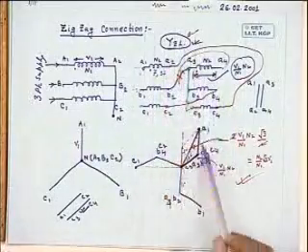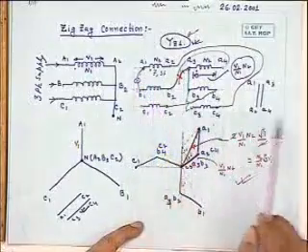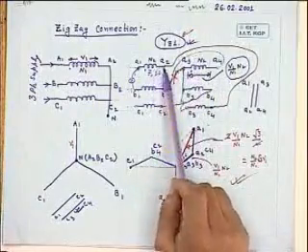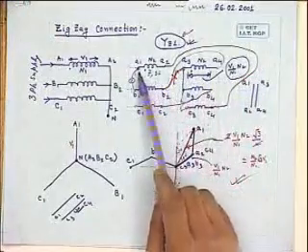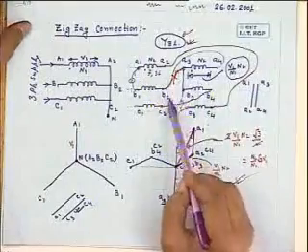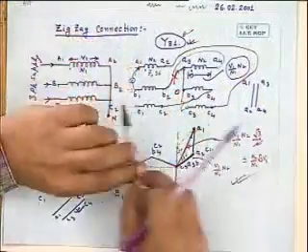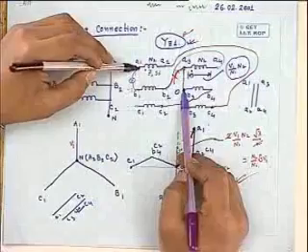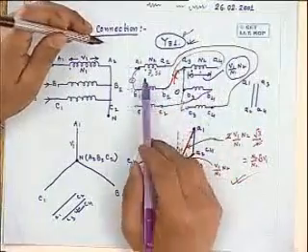Tell me, suppose the secondary is zigzag connected. If I connect between A1 and B1, do you expect any third harmonic voltage to be present on the secondary side? No, because these third harmonic voltages are cophasal. If you mark proper polarity, this voltage will cancel out between line to line. Between one line and its common point, will there be a third harmonic voltage? That is, I will connect a voltmeter between these two points. In a star-star transformer, it will be yes, correct. But here, why will it not be? Can anyone tell me? This will contain third harmonic voltage. This will contain third harmonic voltage.